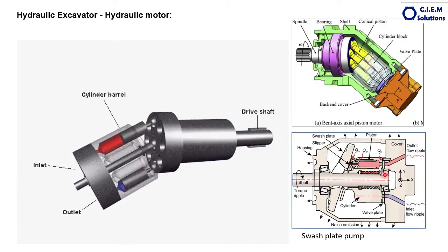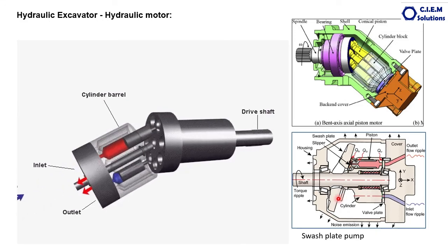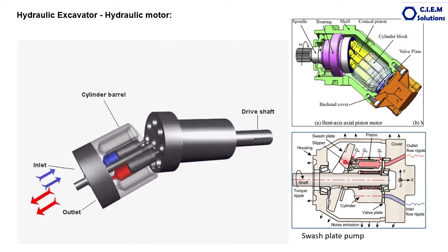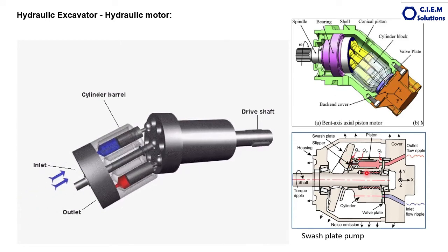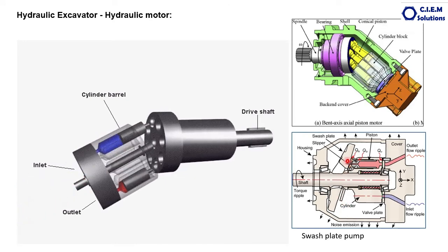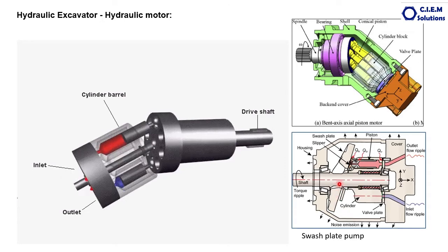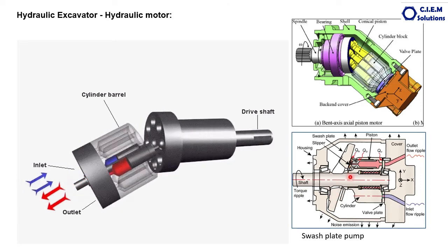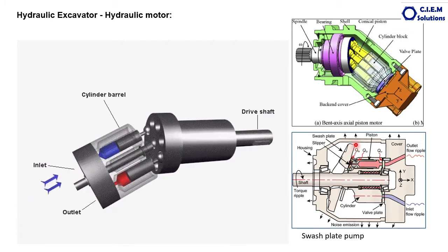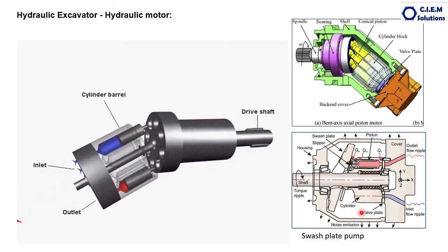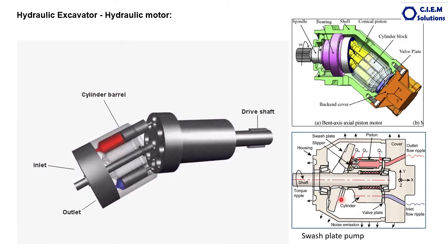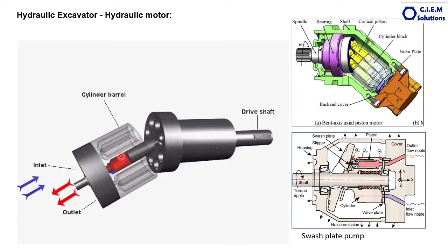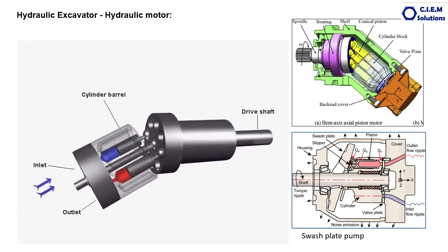How the angle is maintained here is by another device called a swash plate. It's a fixed swash plate. Over this, the complete piston unit is mounted, which freely slides over the swash plate when this complete unit is rotating. This swash plate arrangement provides the angle between the swash plate surface and the barrel housing surface. Again, I am telling you, the angle between these two surfaces is very critical to convert the translational movement of these pistons into the rotary motion of this output shaft.